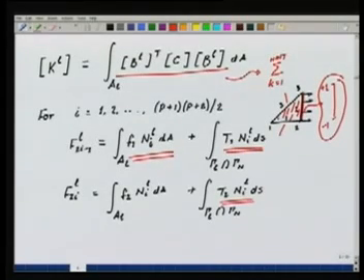So at each integration point I have to compute the values of the shape functions and the derivatives, construct this matrix BL and do BL transpose CB, then put it in. Can't I do this explicitly? Because that will reduce the cost of computation, and if we can do this job explicitly, it is quite easy.